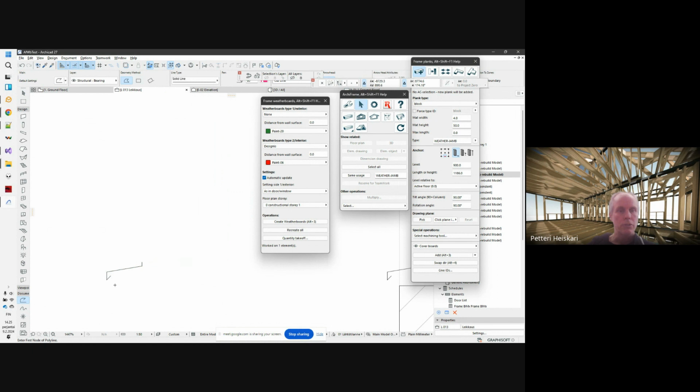And then, instead of having separate line segments, we need to have polyline. So I'll use magic wand, pressing spacebar and clicking this line. And now I have the polyline here. Yeah, here I can see that it's polyline tool. I move it away from these separate lines, and now I can delete these.